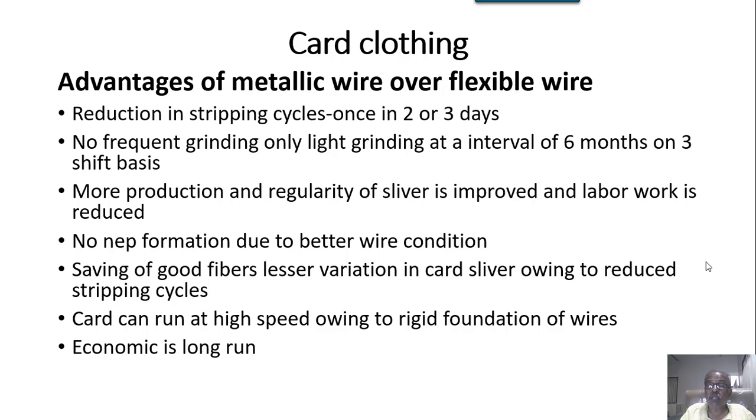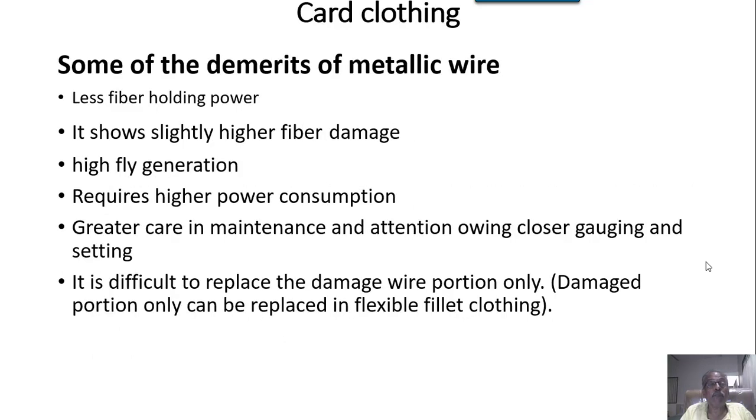I was even using this particular phrase as far as rotor spinning is concerned: the retention of the fiber on the rotor and its plucking off, the peel off of the fibers from the rotor. So retention and release is a very good trick to understand, especially in the context of spinning.